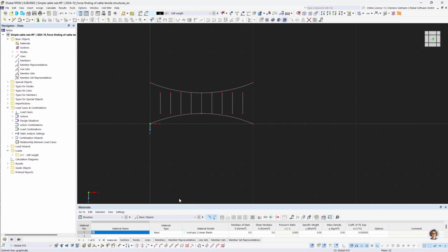If I click on it and hover over the end of a line, it automatically searches for other lines in that plane and creates a preview where an intersection has been found. If you click on it, the intersection is made and the line is extended to the other line. That way, complex intersections can be made quite easily and fast.